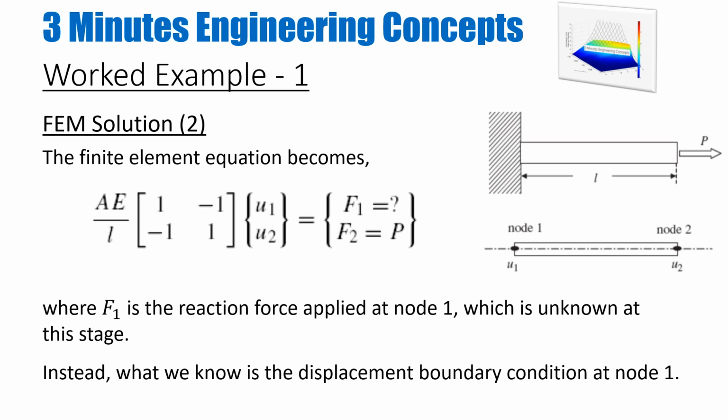So now what I do, once I compute the stiffness matrix, I don't need any mass matrix because it's a static problem, so I don't need that term. So you remember my equation was K times D equals F, right? So in this case, again, there is no global or elemental. They are the same because we have only one element, and also we don't have any coordinate transformation. So I'm using this equation here.